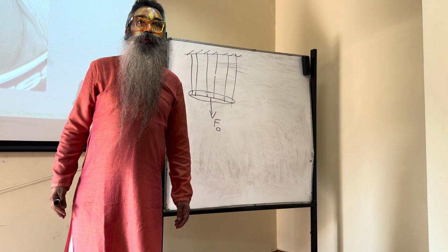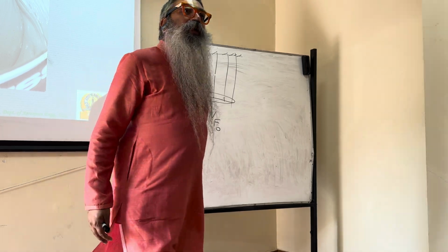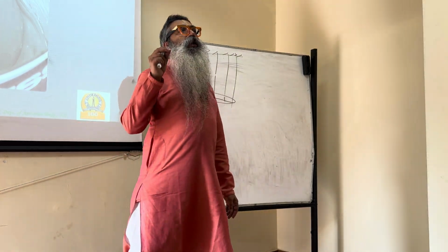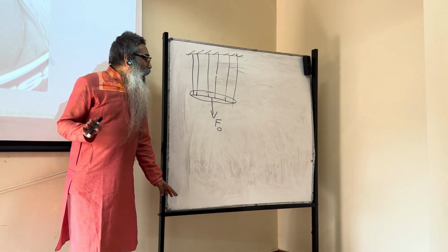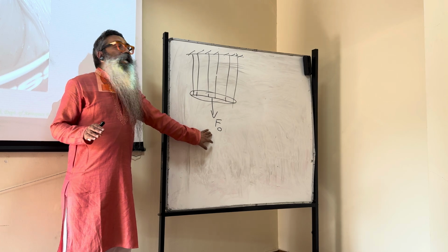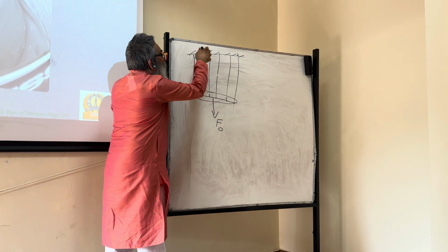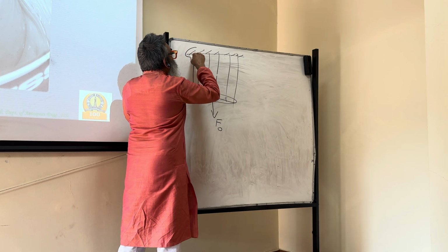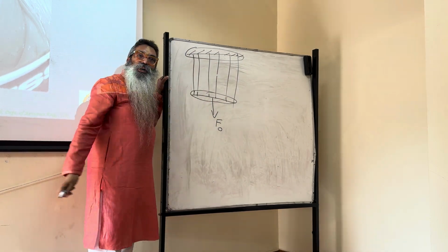I think it still decreased, but not as much. Right, right. So it will decrease by such a small amount that it will be negligible. Okay. For all practical purposes, you will get the same value of F0. Why does that happen? So now, as we said, leave alone the end conditions where Saint Venant's principle is not valid. Only the interiors is what we are taking.